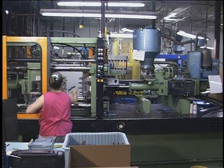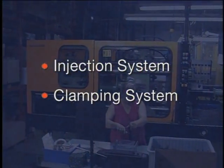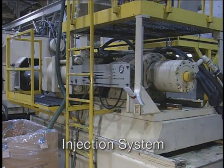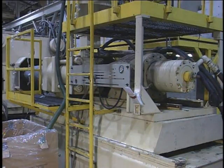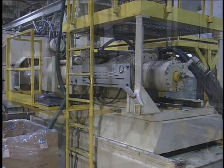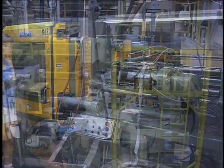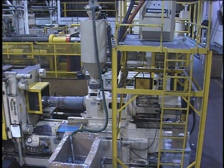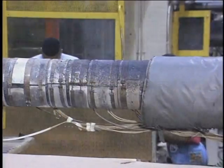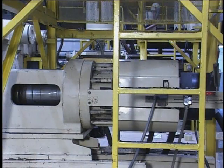All injection molding machines are a combination of 2 systems: an injection system and a clamping system. The injection system heats the thermoplastic material to its appropriate viscosity or flowability and then forcefully injects it into the mold. There are 2 types of injection mechanisms: the reciprocating screw, which is the most common, and the 2-stage screw. The main parts of the reciprocating screw injection system are the hopper, a reciprocating screw inside an externally heated injection barrel, a hydraulic motor, and an injection cylinder.